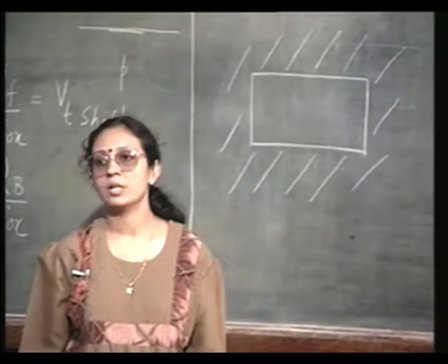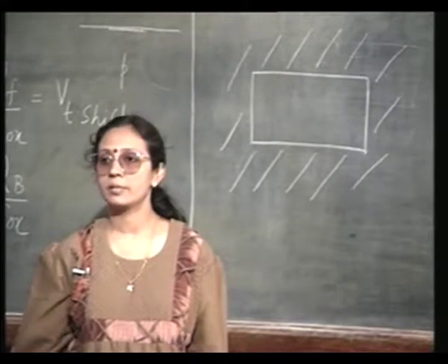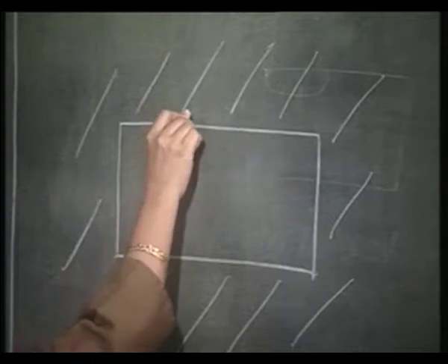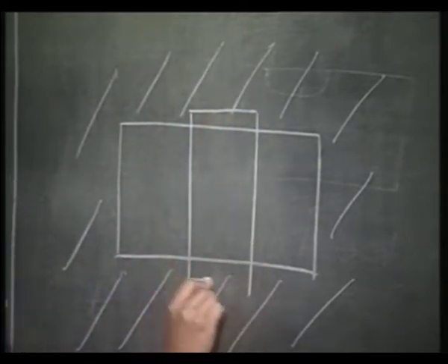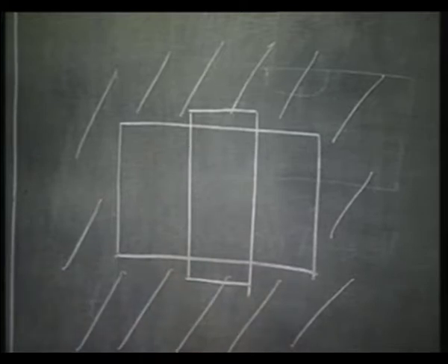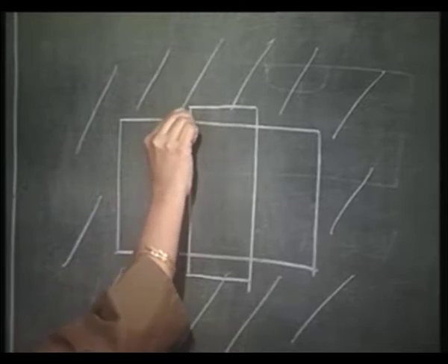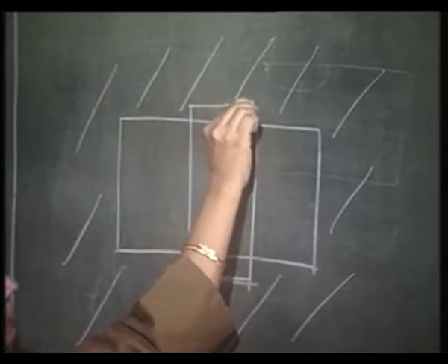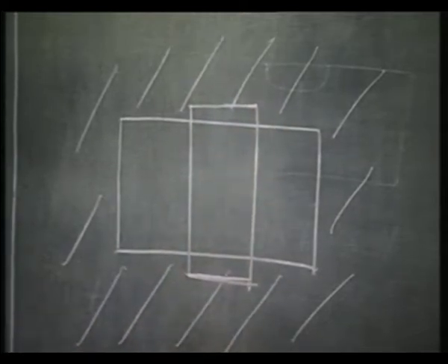Okay, have a thin oxidation done, protect it with the gate metal and then pattern the gate metal so that I have this, my gate.